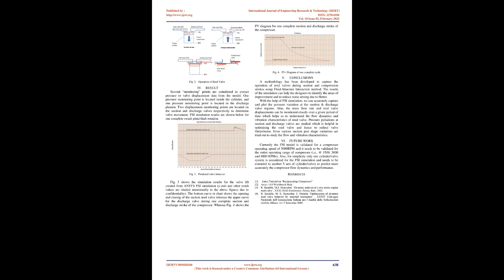Currently the FSI model is validated for a compressor operating speed of 5000 rpm, and it needs to be validated for the entire operating range of the compressor, i.e., at 1500, 3000 and 8000 rpms. Also, for simplicity, only one cylinder/valve system is considered for the FSI simulation and needs to be extended to another 5 sets of cylinder/valves to predict more accurately the compressor flow dynamics and performance.